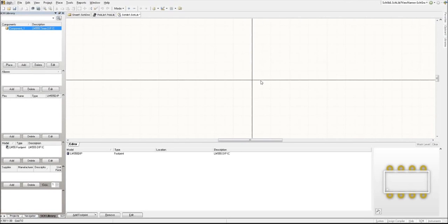So we're gonna start by creating the outline of the IC. It has 8 pins, so what I generally like to do is keeping 2 pins, which is the ground and the VCC, at the bottom and top, and then I would simply have the other pins on the sides. And what I mean by that is that you're gonna have 1, 2, 3 pins, and 1 ground and 1 VCC on top. So let's start creating the pins.